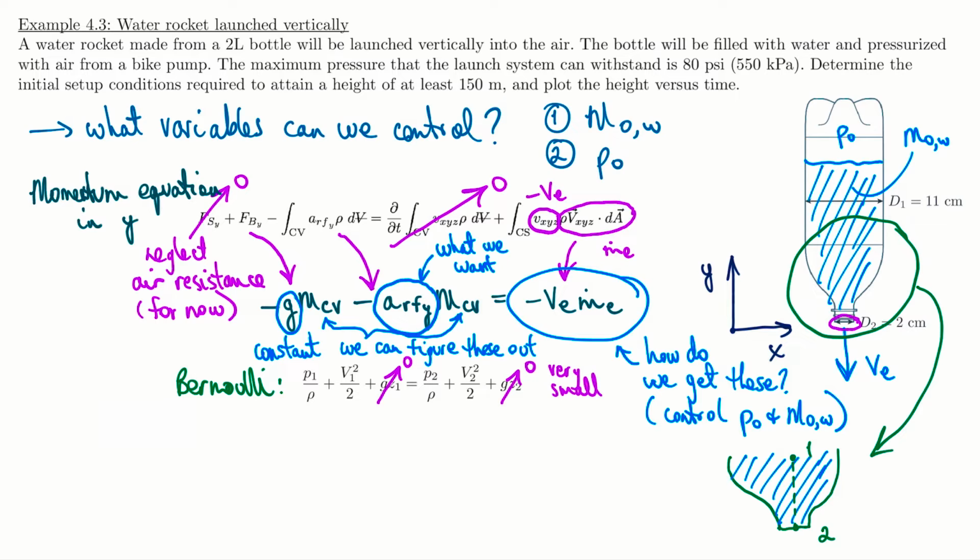And now V1 as well is going to be very small, but maybe I'll show you the calculation for that one first, and that actually is a nice way to use another equation we know. What I want to show you is that V1 is actually quite small in this equation compared to V2. If you think for a second, how can I relate V1 and V2? Similar again to the previous nozzle question, we can use a mass balance because we know mass is going to be conserved as it flows through the bottle. So there's the equation there again from the video.